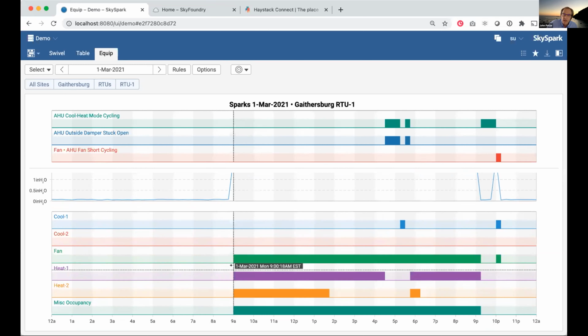When the fan turned on, 2 stages of electric heat started simultaneously. We can see they started together. There was no soft start or staging. Now, as the facility operator, I look at that and think, wait a minute, that doesn't look right, right? Our understanding is that all of our units are programmed to soft start, only bring on the first stage of electric heat first, and then if you can't maintain load within a certain amount of time, bring on the second stage, right? To manage our energy demand. But what are we seeing here clearly? We're seeing that they both came slammed on at the exact same moment in time.